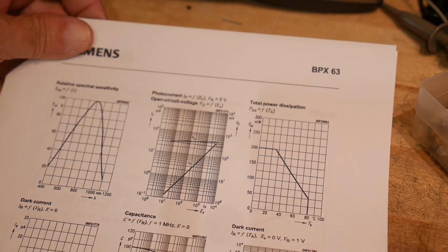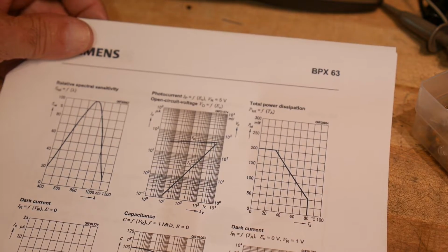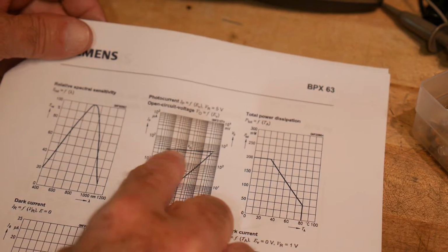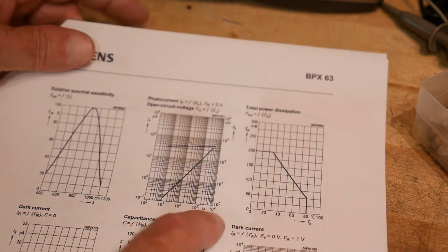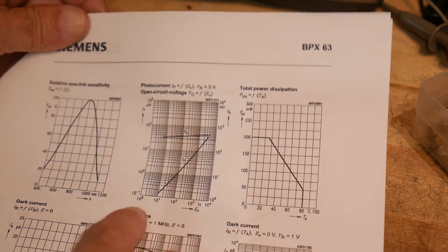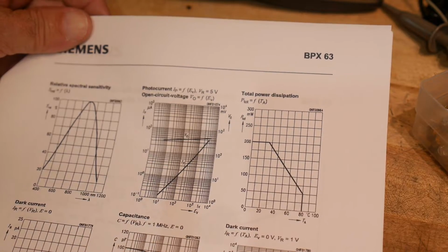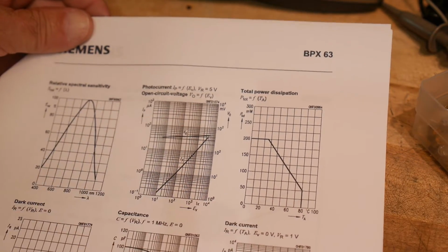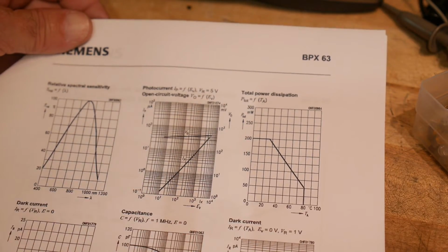If people say, well, I'm going to use the voltage change of the diode, not the current change of the photodiode, that's this graph here. You read this scale. So actually, the voltage doesn't change very much with brightness, but current does. So it's much better to run photodiodes in this current mode.